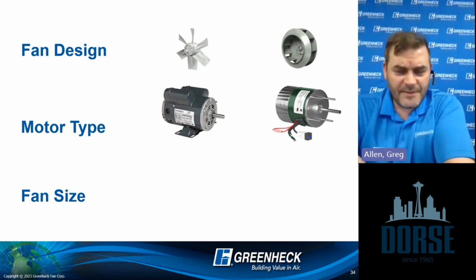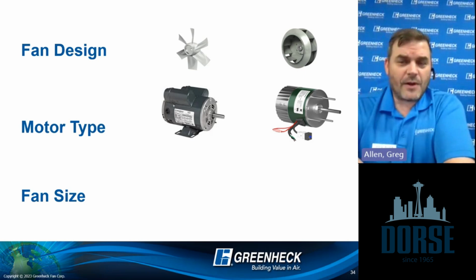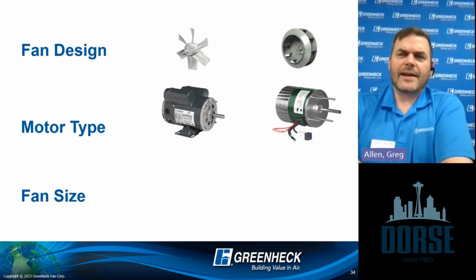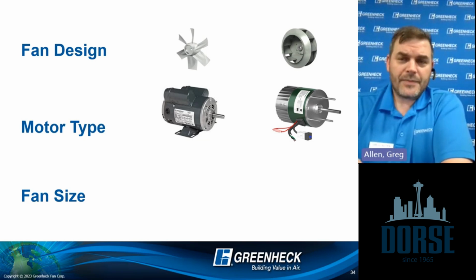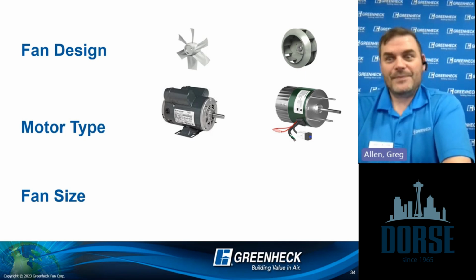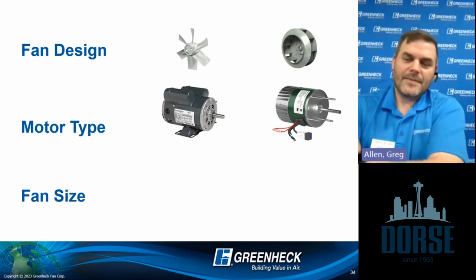When you get up into the three-phase world, three-phase AC motors are much more efficient. But there's also EC motors that are even more efficient yet up in that range. To give you an idea, a 2-horse AC induction motor is usually around 86.5% efficient, which is really good. An EC motor at 2-horse, you can get upwards of 91% efficient. So your gains are smaller, but they impact the wallet more as far as savings, picking up that 5 or 10% on that end.